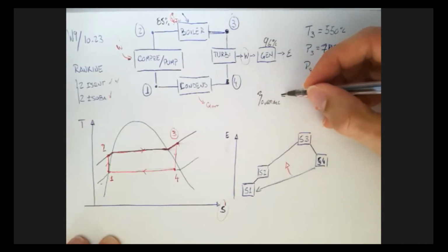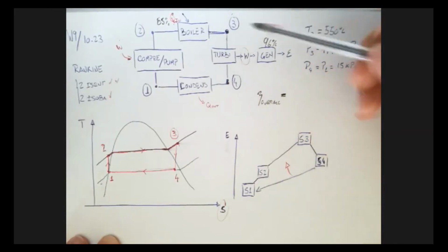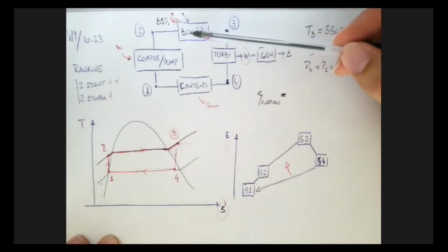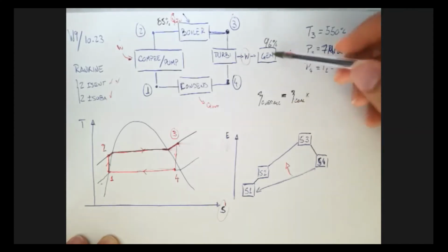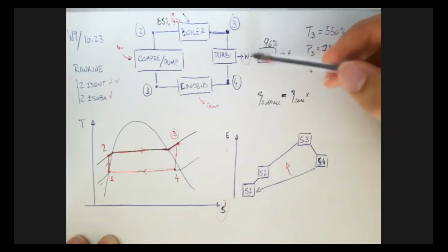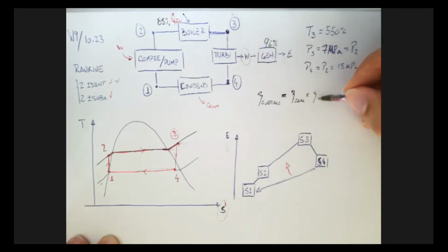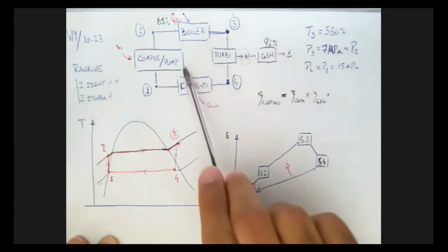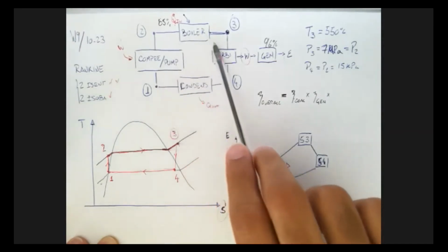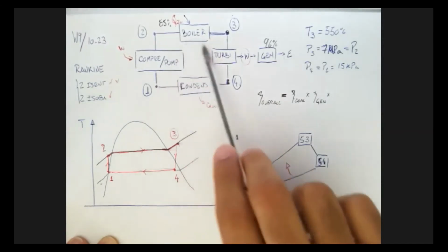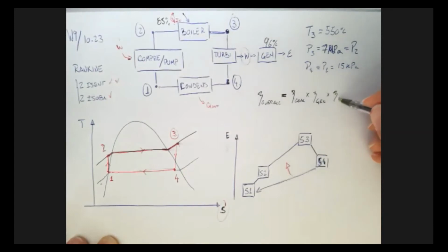The overall efficiency is always a combination of the individual efficiencies, right? In this case, we have the efficiency of coal giving energy to the water, which is 85%. Let's just put efficiency of the coal, the boiler too. We have the generator, which is taking this work and transforming it into electric energy, operating at 96%. And we have the actual plant, the one that's getting the water, compressing, boiling it up, using the turbine, condensing. So that's the thermal efficiency of our cycle.